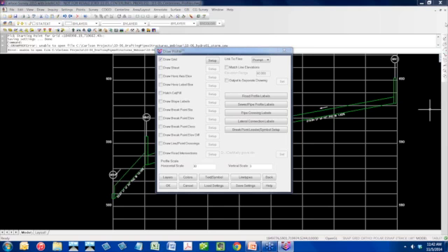All right, Karen, while you're looking that up, I'll just finish this part up real quick. So the last thing. She wrote, when you do a standard roadway profile and you want a 25-foot left and right offset, is there a way to get the profile graph to print out the elevations of only the center line proposed and existing elevations and not the 25-foot offset elevation label?